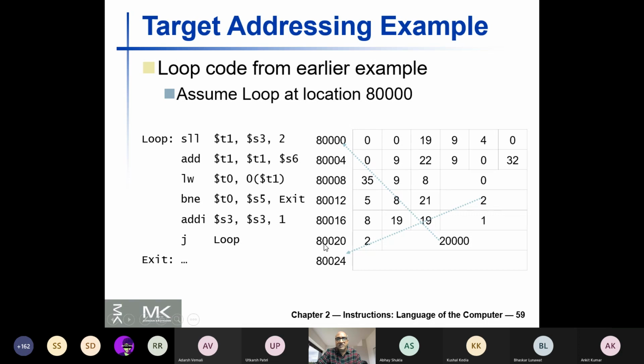Because here, from this PC, there will be other elements and the address will be much higher, but just for this illustration purpose, only the least significant 5 bits are given here. So if you take a PC, the higher bits will be something else, and you take the 4 higher bits and then append these 80,000, because 20,000 into 4 is 80,000. So it will go back this way. That way you can calculate the addresses in case of branches, whether conditional or unconditional.